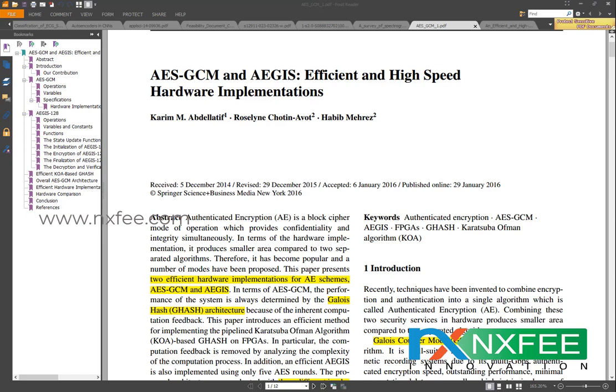In this work, the 512-bit plaintext data is processed using 4 segments of AES 128-bit encryption operation to improve multi-block encryption efficiency. The major novelty of the proposed work is the integration of overlap-free Karatsuba multiplication, a parallel GHASH scheduling algorithm, and CLA-assisted data path optimization into a unified FPGA-based AES-GCM architecture for reduced critical path and improved throughput performance.